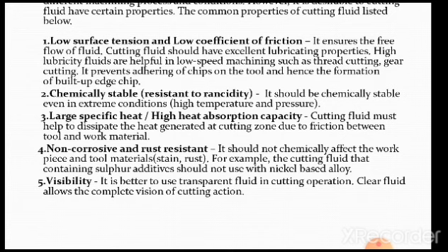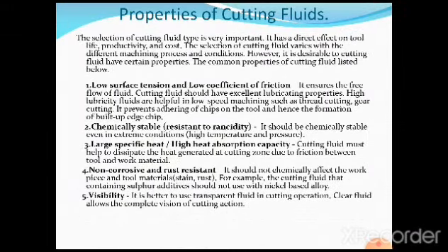Visibility: it is better to use transparent fluid in cutting operation. This is very, very important because generally the cutting fluid used should be transparent so that it is possible to view how the machining process is being carried out by the operator at every moment of time. Clear fluid allows the complete vision of the cutting action. That is what I have told. As far as possible, if the cutting fluid is transparent, it is possible to see what is happening in the cutting zone.